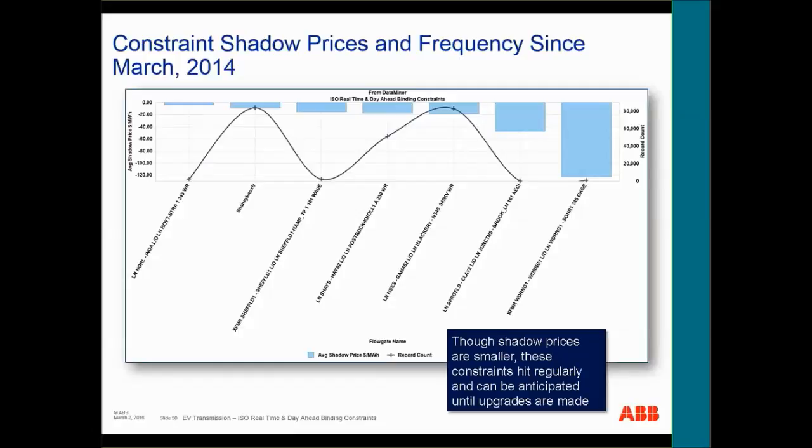So if you were to look at this, combining it with the lower temperature and the lower demand that we were seeing, I would basically expect that this area is just regularly overloaded, and this would be a great spot to be that new wind farm that's maybe alleviating some of the congestion. Definitely not a place where you want to go on the other side, where you're potentially going to be curtailed.